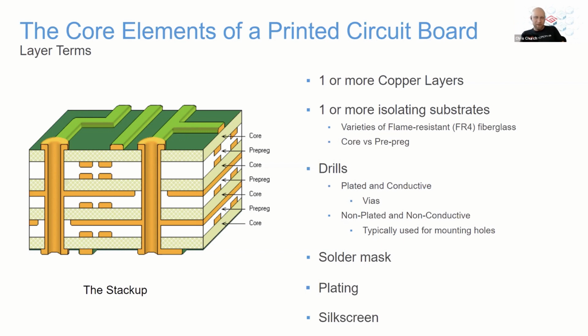The next point in there we have is the plating. If we think about when you get a PCB back from a fabricator, what you're actually seeing on the outside is not the copper. It shouldn't be visible to you because copper oxidizes very quickly. And if that were left exposed to the air, not only would you be losing some of your copper material because it would be turning into that oxidized copper, but that oxidized material itself is a contaminant that will damage that joint.